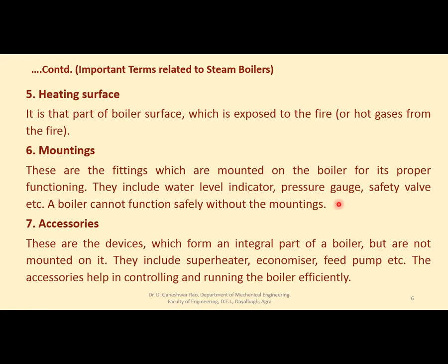Pressure gauge. The pressure gauge indicates the pressure inside the boiler shell. If it exceeds the limiting value, the boiler may burst, right? If sufficient pressure is not there inside the boiler, steam may not go to the required place properly, right? So a proper pressure has to be maintained inside the boiler while heating water.